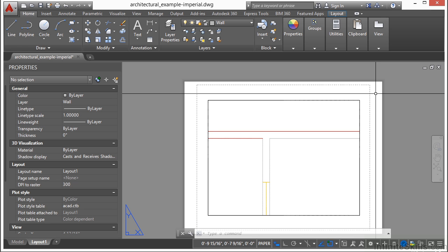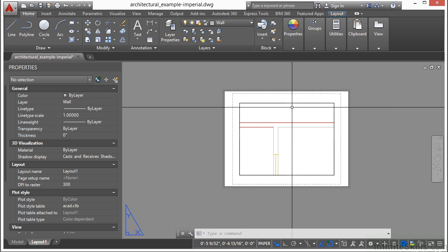Make it by layer all of the time. You say, well, I have this one line. It's only one line, and I need it to be this specific color, and I need it that way all of the time. That's fine. Make a unique layer then for that specific circumstance. And that's okay to do that. Because then, what if the circumstances change throughout the life of the project? That does happen all of the time. So just keep that in mind. It's in good practice to draw everything by layer.